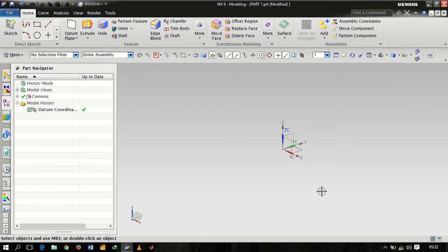Anyways, yeah, so this is the first screen that you get when you open a new file for modeling. Let's get acquainted with a few basic things which you would require. I hope it's better if you note down a few things. The middle click, when you click the middle mouse button, it will help you rotate the body. Just click your middle button and start hovering your mouse, and it will start rotating whatever body you have. In this case, just the axis or the planes.